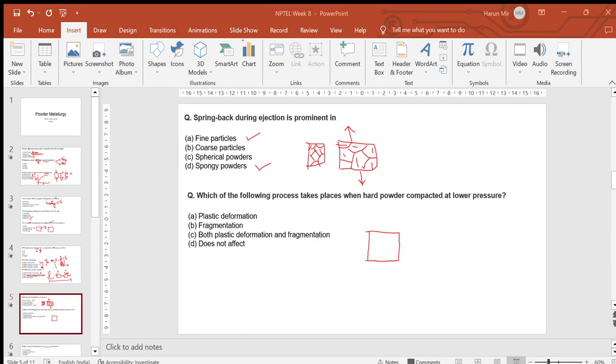So the slip casting method is one of the types of slurry casting, and in slip casting you have specialized molds, because you want removal of your binder by mechanical forces. So you just have to answer what kind of mold is being used and what is the action by which this binder is being removed. For slip casting, we use a porous mold and capillary action. Right, because we are using a porous mold.